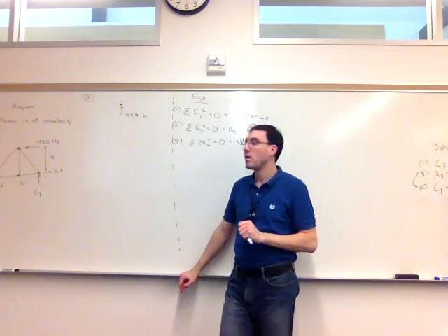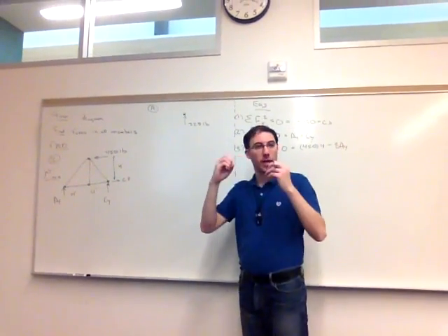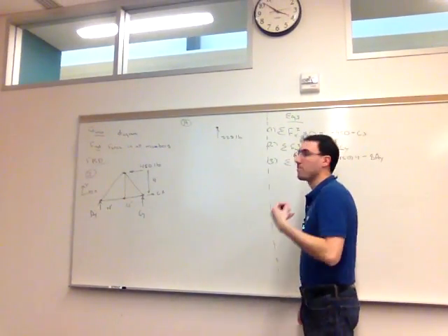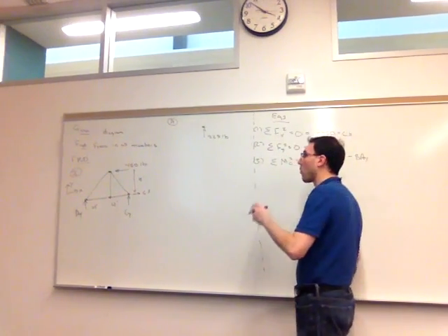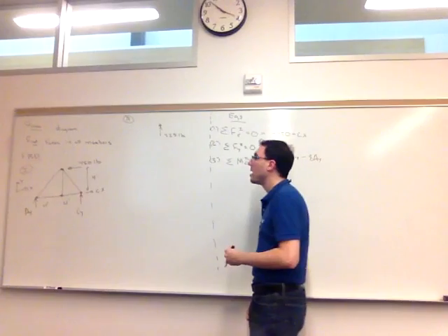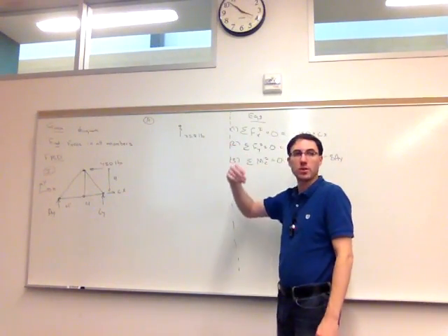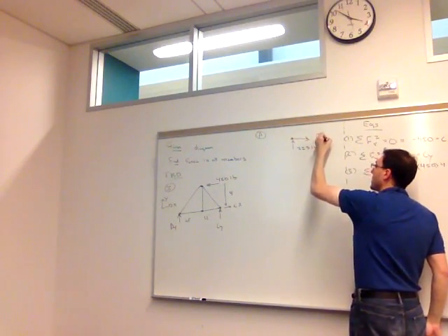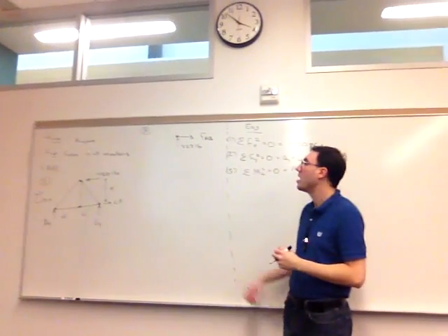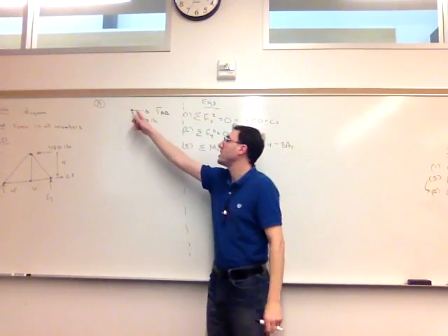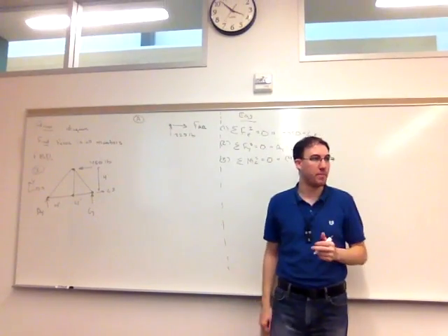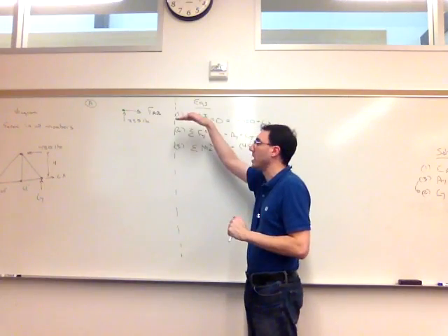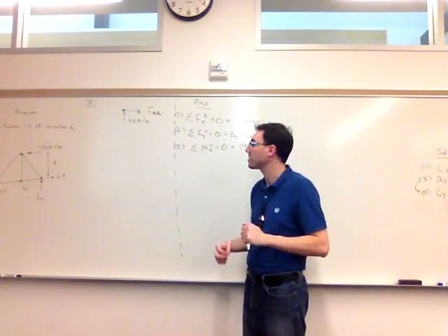Force in AB. Right, so the member AB is pulling or pushing potentially on the pin also. The way we model it, part of our assumption of trusses is that the force in members act only along its length. And for our solution, I'm always going to be assuming tension. So I'm assuming that the force in AB pulls it to the right. If it's in tension, that means that the forces are always coming out from the pin. So FAB has to be either left or right because it's along the length of the member. I'm assuming tension, so it's to the right.